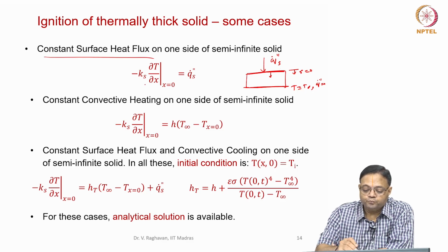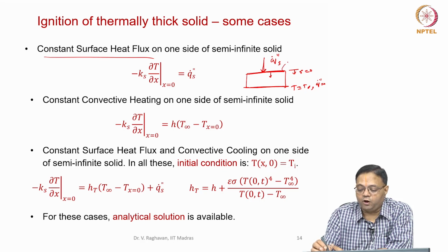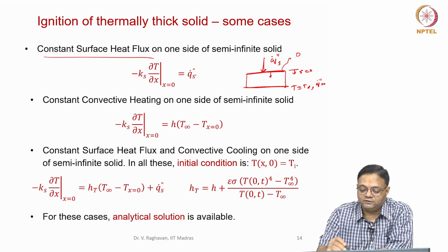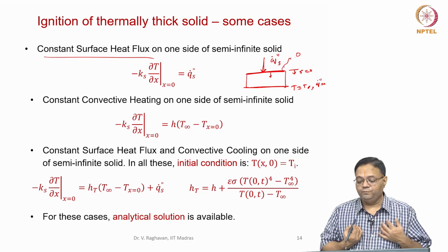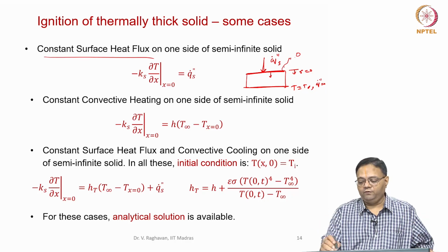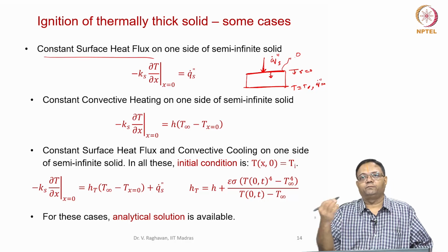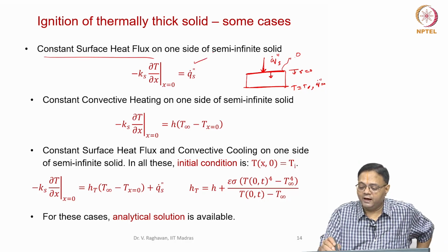Okay, now whatever flux comes in, I do not take into account the loss, this is 0. So, whatever comes in at the surface is conducted inside. So, based upon this balance, the surface temperature will increase. My objective is to find the rate of increase of the surface temperature due to a given heat flux and conductive heat transfer within the solid from the surface. So, this is the boundary condition I use. Here, any other boundary condition?